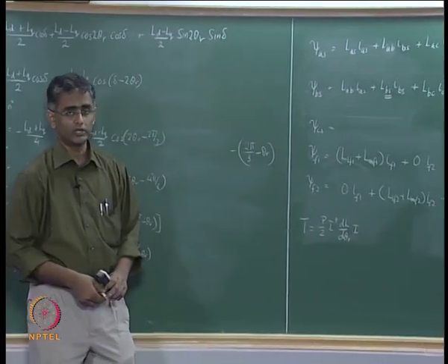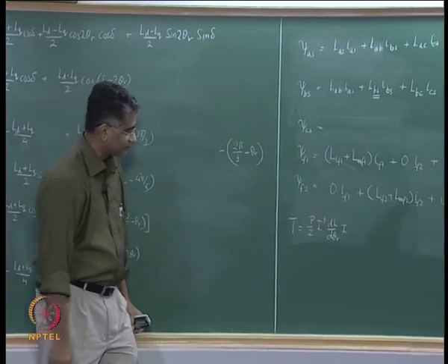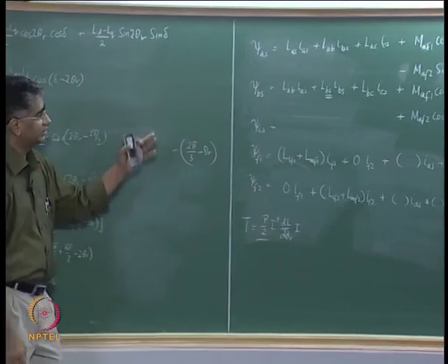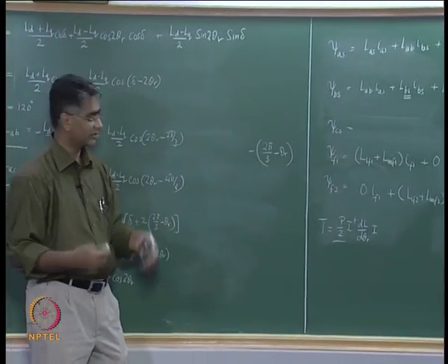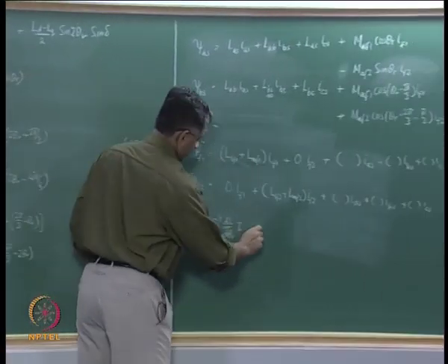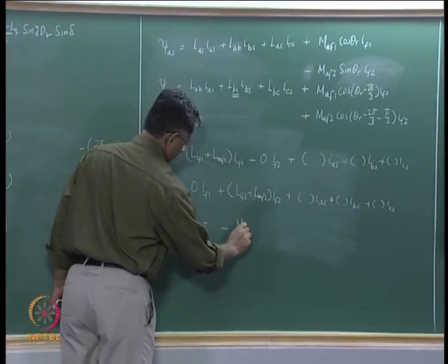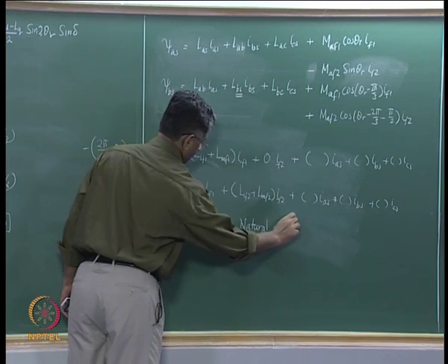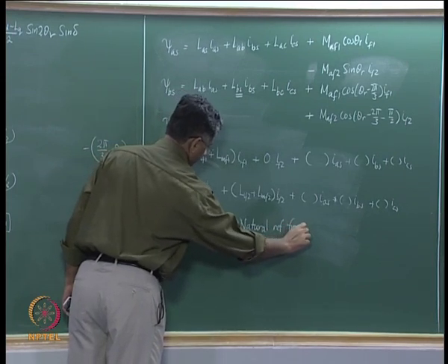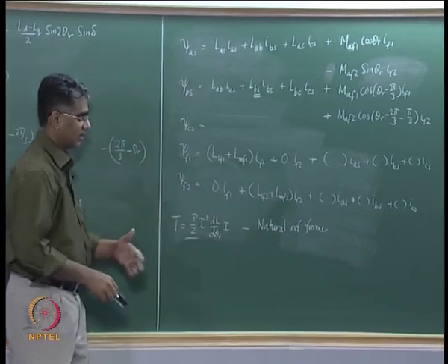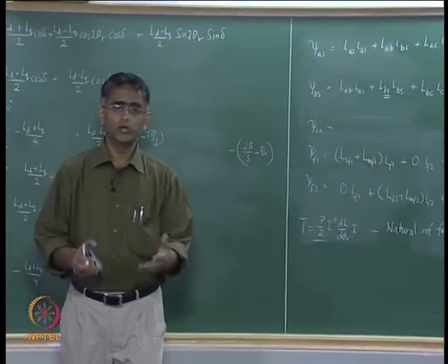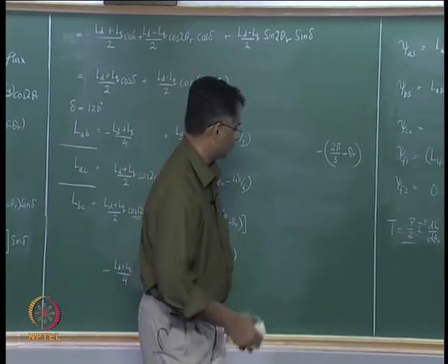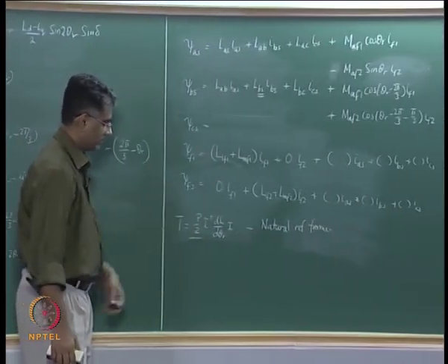So it is p by 2 times this expression. This equation, again these set of equations, as for the induction machine, they are said to be in the so called natural reference frame, because the variables are as they would be in a real life induction machine, naturally found variables. So it is called as natural reference frame.